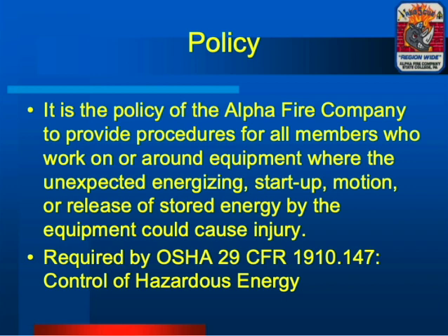So with that, a plug and a cord connected to equipment are not covered in this policy. So we understand that the plug or the cord is the only source of energy for the machine involved in the operation, and the equipment remains unplugged during any operational activity. The plug is under the exclusive control of the member performing the operation, and there is no source or stored potential energy present. So what it's really saying is once the machinery is unplugged, then we reduce the potential for any type of stored energy being present there.